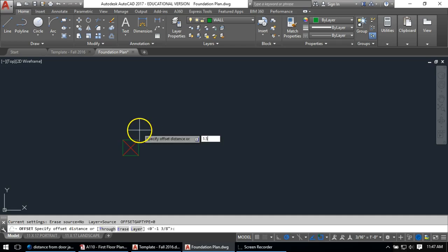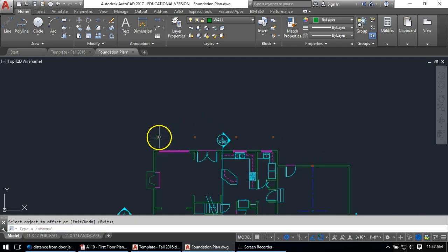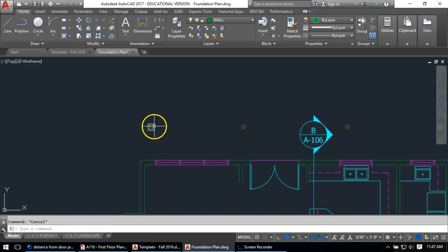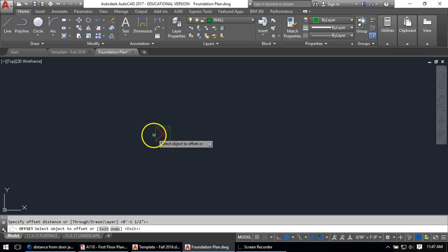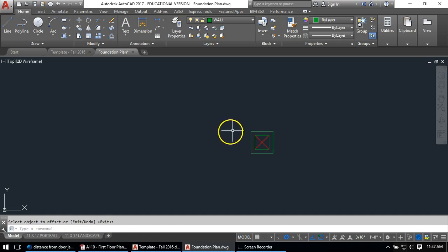What if I offset 1.5 inches? I'm going to say that looks better. Yeah, so there's no dimension. Actually, I'm on the wrong side, because on the back side it doesn't have that offset. It's only on the front side of the house. Erase. There we go. Sorry about that. Only down here I'm going to offset 1.5 inches to do this detail here, here, here, here. And the deck comes up.